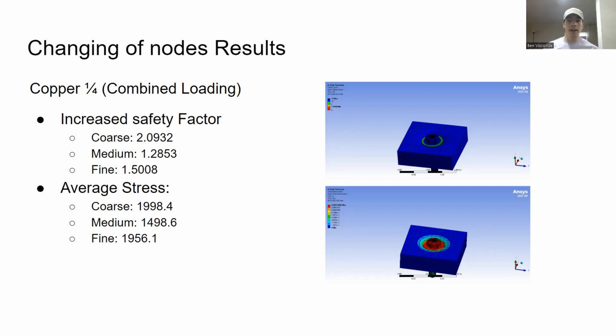But with this in mind, you don't want to set your resolution all the way up to 7 or the max resolution, just because it'll take so much time to complete your analysis and your calculations. Rather, the 4 or the 5 level will suffice and you'll get your accurate data from there.